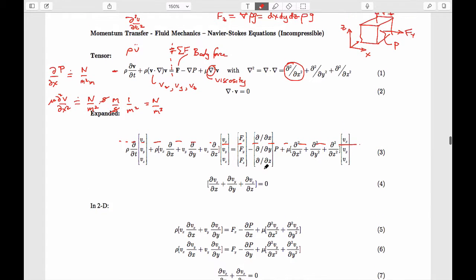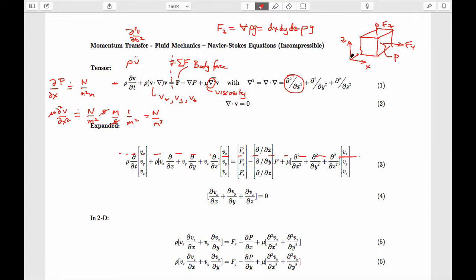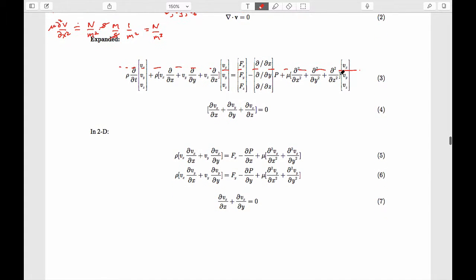If we want to reduce it from three dimensions to two, then we would just get rid of the z direction and have it flowing in the x and y plane, however we want to orient it, either horizontally or vertically. And if that's the case, then we can just get rid of all the terms that involve z, such as, for instance, this, and this, and this, and this, and this. Because clearly, the assumption is the velocities are only within this plane, xy plane. So the velocity in the z direction, by definition, has to be 0. So it seems reasonable that we can drop that out.